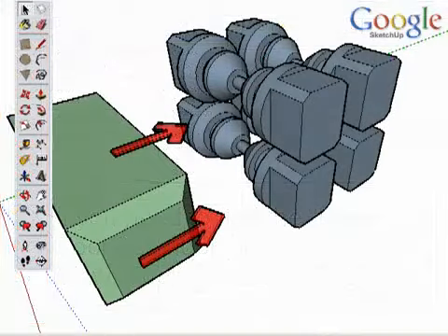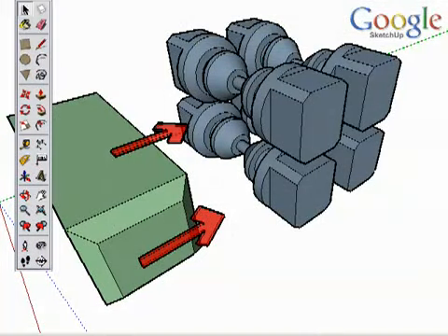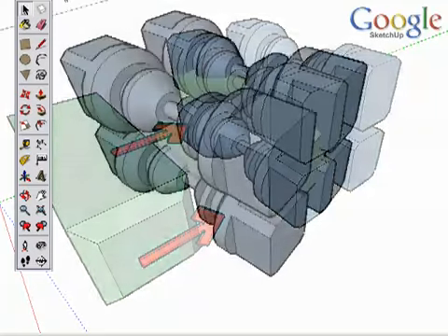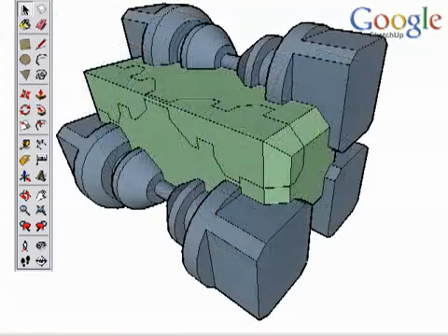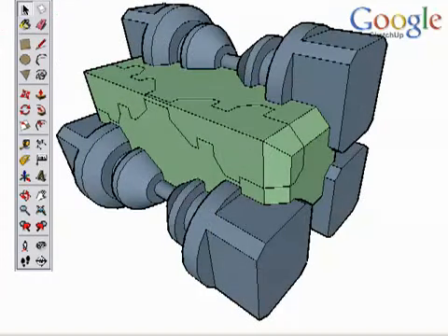You may not know about the ability to intersect models, as this feature is only available through context menus. However, it's a very powerful modeling tool no SketchUp user should be without. Essentially, it allows you to overlap multiple objects and creates edges and surfaces where those objects intersect, resulting in new and potentially complex geometry.